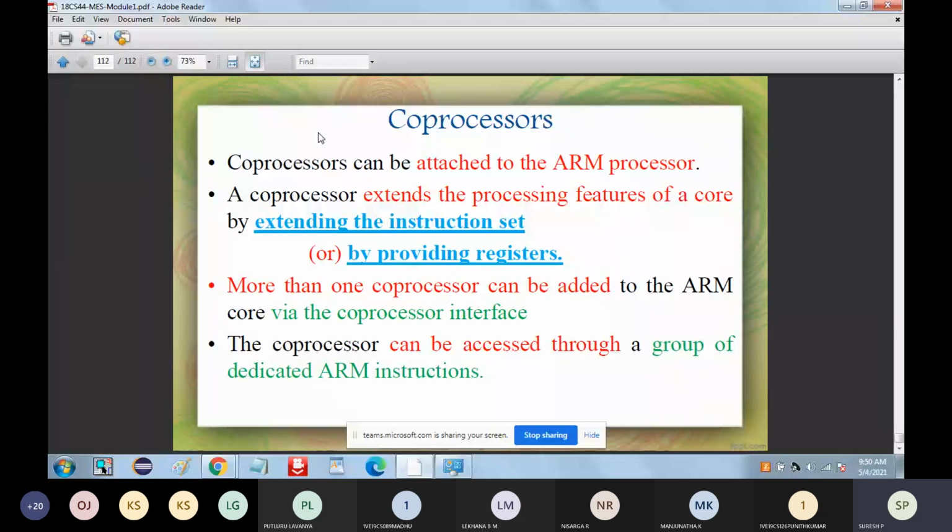There are four fields in your CPSR. What are the four fields? They are flags, status, extension, and control. Okay. Once you have this, we discussed conditional execution. Last, pipelining, which is also important from the examination point of view. Apart from exceptions, the vector table, and interrupts, the last one is core extensions. In the core extensions, you have four.